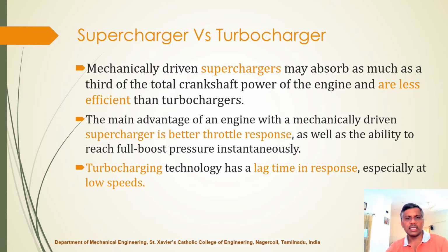But you can see that turbocharged technology is now used in almost all diesel vehicles. The problem with turbocharging is that at low speed it doesn't work, because you should have a proper velocity for the turbine to rotate, since the turbine uses the exhaust gases coming out of the engine. That should be sufficient enough. It should have sufficient velocity and sufficient quantity to run the gas turbine.